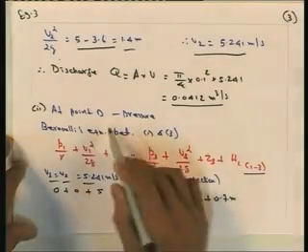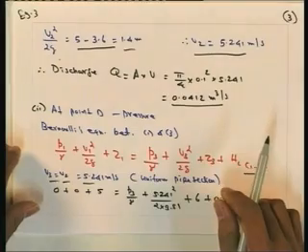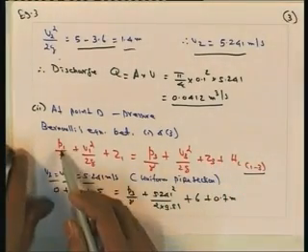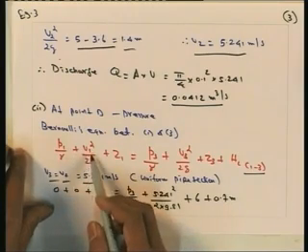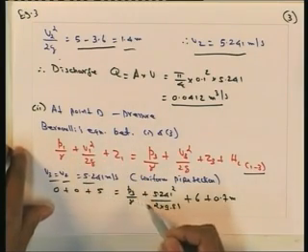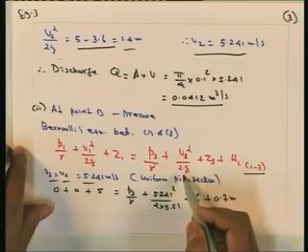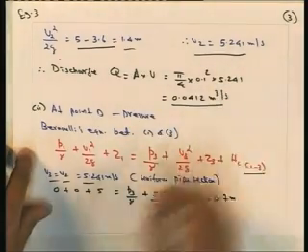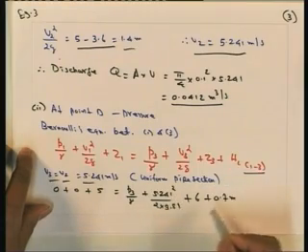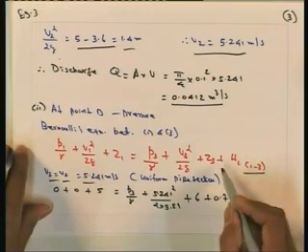Finally, if you write the Bernoulli's equation between sections 1 and 3, P1 by gamma is 0, V1 is 0, so 0 plus 5 is equal to P3 by gamma plus V3 square by 2g. V3 is already found, 5.241, so 5.241 square by 2 into 9.81, plus 6 is the Z3.